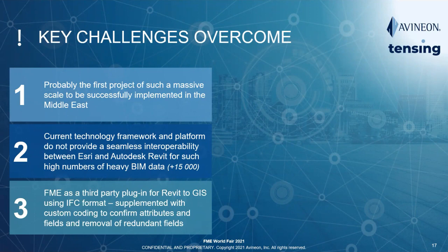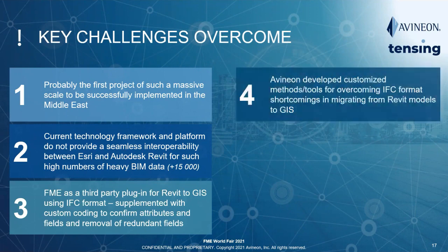We use IFC format here. And this was supplemented with some additional custom coding because we wanted to make sure that all the attributes were confirmed as we were loading data. And every now and then it seemed like there were some redundant fields being generated. And so we were able to go through and do quality control with some additional custom coding. But FME was like the workhorse in this thing, which really helped.